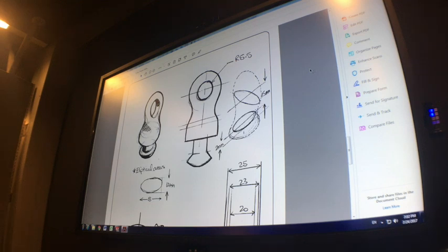For a loft, you typically need multiple sketches or multiple faces already existing to loft between. In this case, we've got a circular surface at the top from our revolve, which we're going to use. Then we need to create 2 more ellipses, so this loft is going to use 3 different segments.